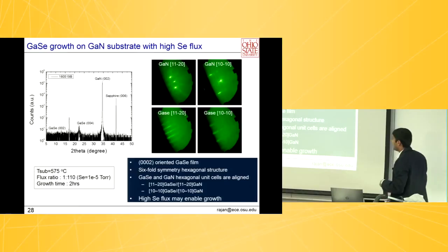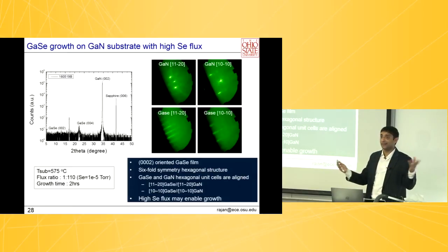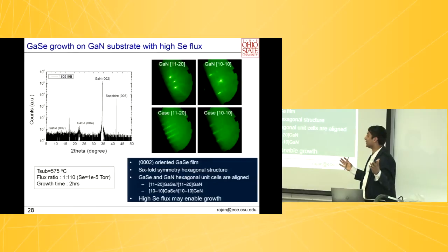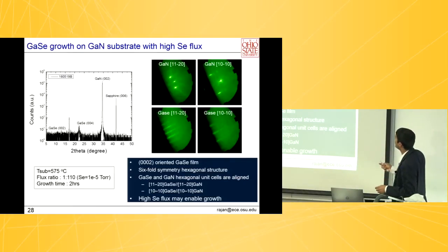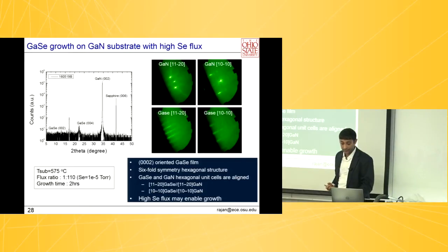Okay? Of course, the reason we started doing gallium selenide was that our e-beam source had not come in. Gallium selenide is a very painful material to work on. The moment you take it out of the chamber, it oxidizes and it's gone. So maybe it's useful for some transient electronics, but it's just a very painful material to work on. So we're going to move on to MoSe2. But we're learning a lot about how to do these things. And I encourage you to talk to Chung-Hee about all the details about how this happens.